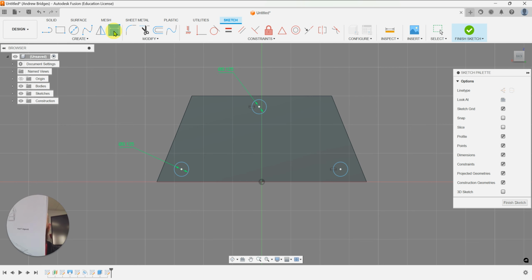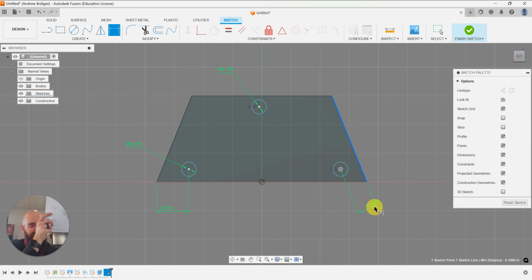So, looking at my drawing, in the 4th part of the drawing, it looks like I am a distance of 0.125 up and a distance of 0.275 across. So from here to the corner in the horizontal dimension, 0.275. Now, be careful. Don't go from the center to the line. That's going to give you an aligned dimension. We don't want that. We want to go from the center point to the point.